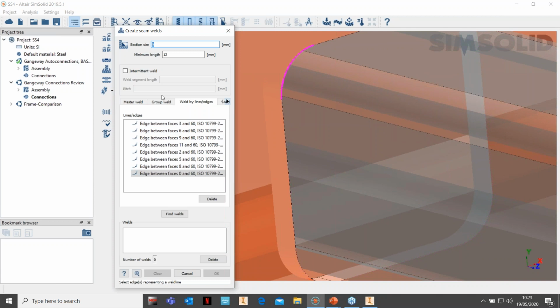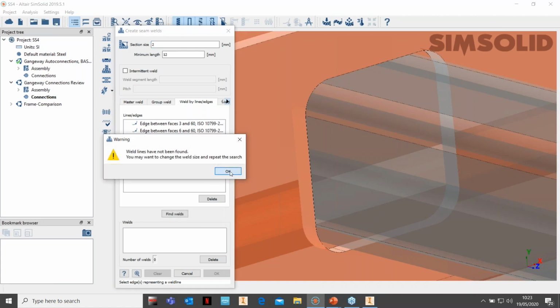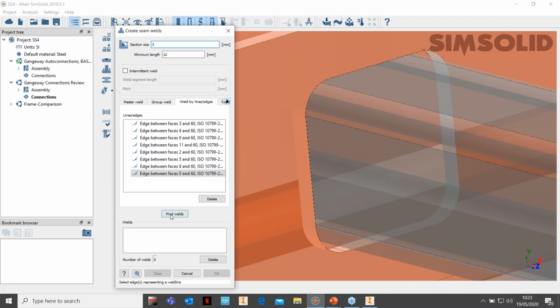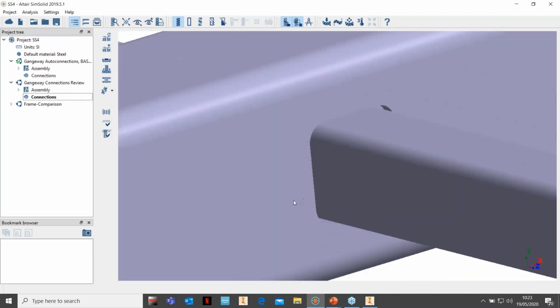And let's just start. Now I have got an intentional gap between that box section and the hole in it. So I'm just going to try 1 for a moment and see what happens. You get this message. And then we can increase the tolerance to 2. And it's because it's 2 and 2, so maybe need to increase that slightly to 3. And there you go. And then also what you could do here, a fourth option, if you have created weld geometries inside Inventor, then you can bring the fillets across, and you can use the fillets also as physical weld symbols.